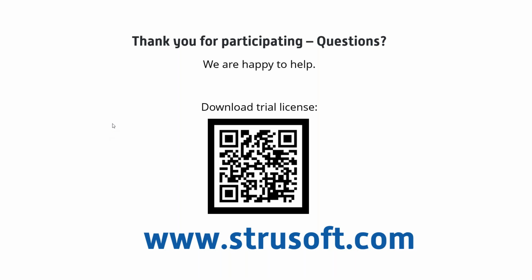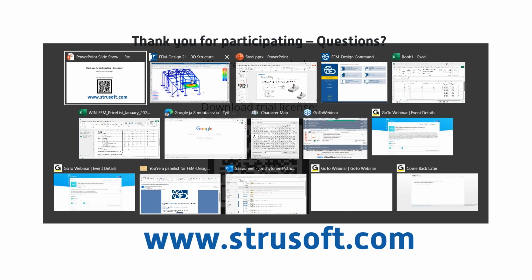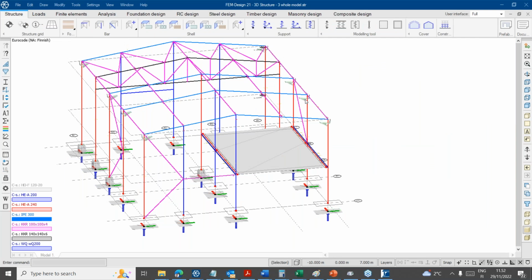What is the approach to model steel beams under the concrete floors, and how do you get the right distribution of forces to the beam and the floors? Usually the concrete floor takes too much of the forces, and the beam takes too little. It depends on what kind of floor you have. If you have a one-directional floor, like hollow cores, I can go back to the model and see what has been done in this model.